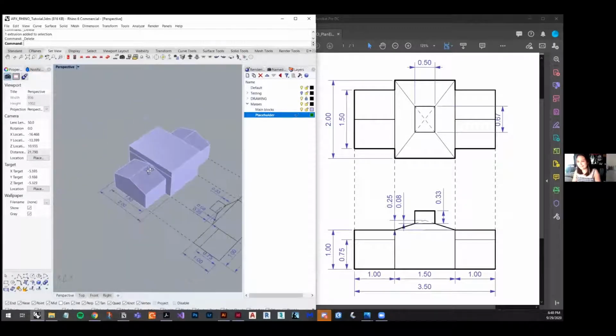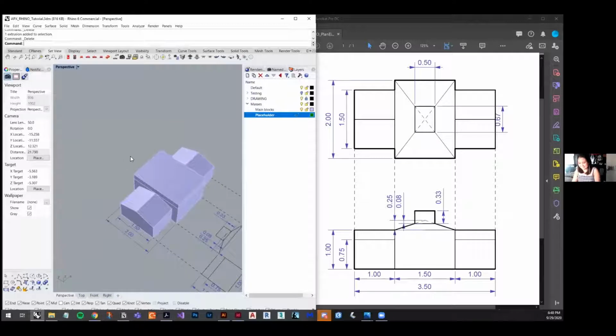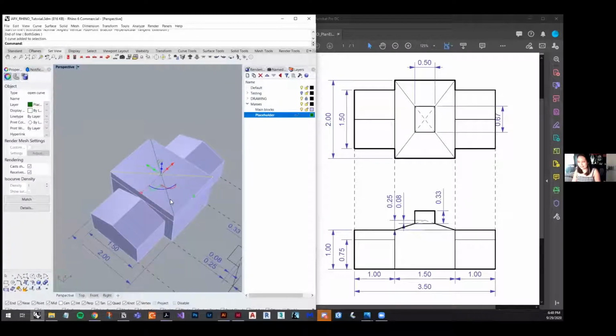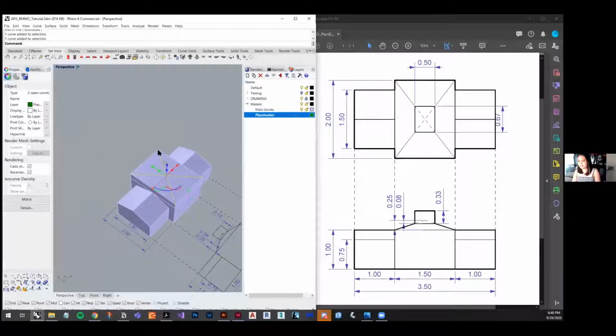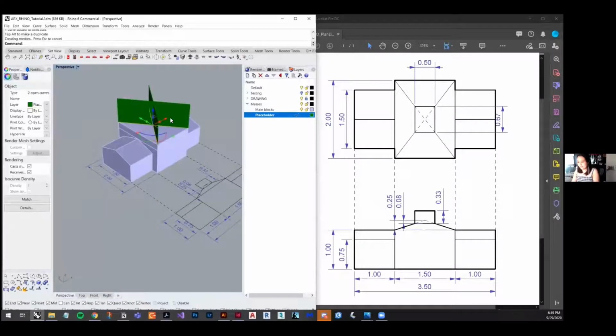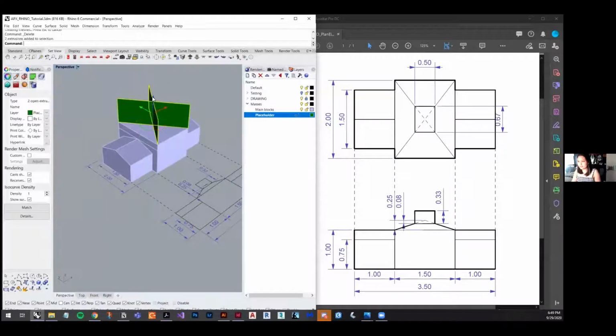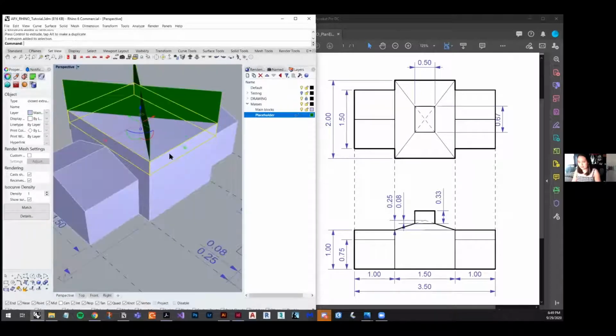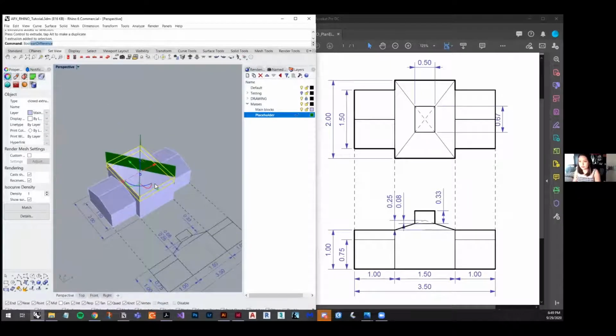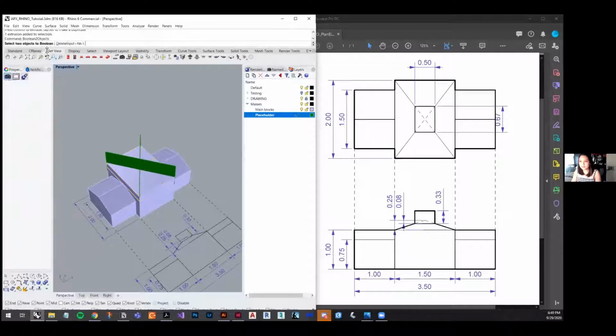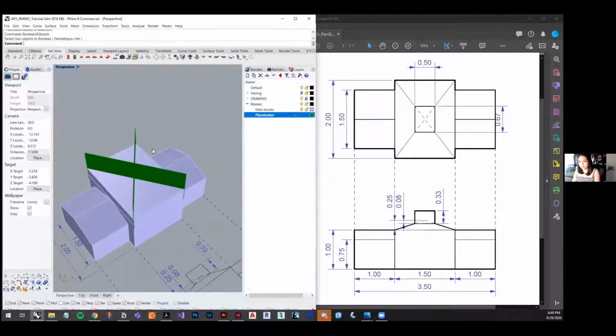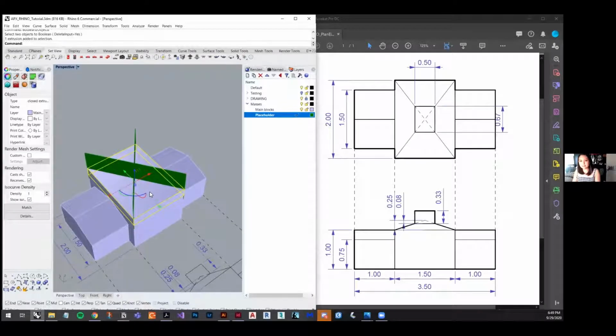Oh yeah, sorry, that's actually what I was gonna say. Okay, I wasn't sure. Yeah, so another way that Maria stated, actually, here, we're gonna take our curves again, we're gonna extrude them upwards. We're gonna delete those. We're gonna take these and we're gonna bring them down so that they're intersecting. Boolean, when you do, yeah, you can Boolean Two Objects. I actually like doing Boolean split. It does the same deal, except like Boolean Two Objects, it makes it into these two objects, whereas Boolean split, it's like splitting it.